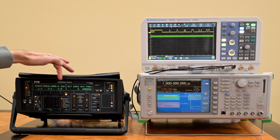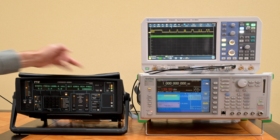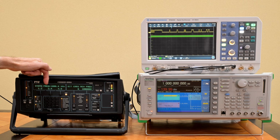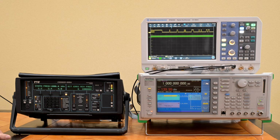So the analyzer screen, we can see we got a frequency coming in at 1 megahertz here. So that's indeed also the send frequency. So the loop is properly working. And I have not observed any bit errors yet. He's already into testing now.